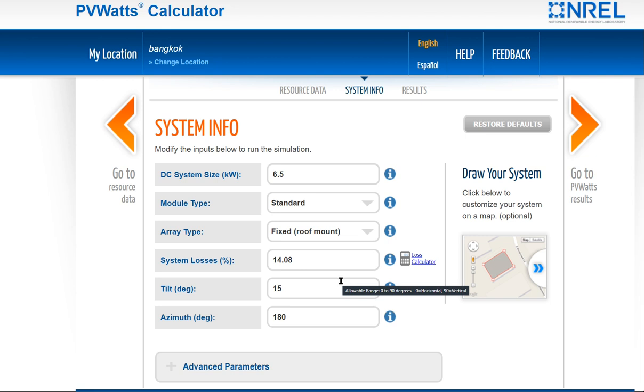Obviously, there are other factors involved here too, but we're going to look at only the energy difference and see if we can make any conclusions. So we're going to start at looking at 6.5 kilowatt of panels. It's about 14 panels around there somewhere. Doesn't really matter because the numbers don't change depending on this. It will all be in relationship to each other anyway, so you can put anything you want there. And then the tilt is perfect, and this is south 180 degrees.